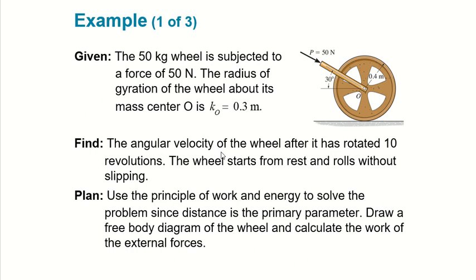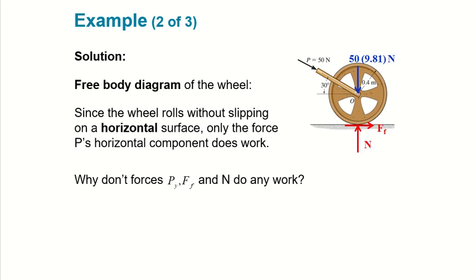Before we do this problem, we will draw a free body diagram, because we're given a little animation diagram here. We're going to transfer that to the force diagram, then calculate using these external forces. In his example, he just put it right in there, but you can also take it out, draw a circle with the center O, and put all of this information: your force, your angle, and your radius, the distance from the center to the circumference. Gravity acts down there.